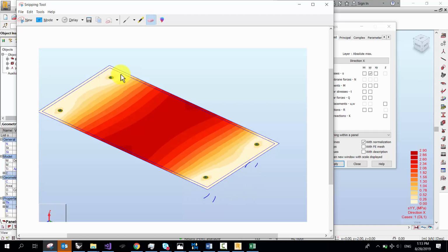So what if we just did, I mean, you could change this very easily actually, but in this case, if it's up and down, they would all be getting at least that, right? And then one of them needs to get this direction, or else it slides left and right, and another needs to get also this direction. But then it's not stable rotation-wise, so it probably needs this as well. So it can't move this way, it can't move this way, and it can't rotate this way. So it's stable. So boundary conditions, we've over constrained this problem.